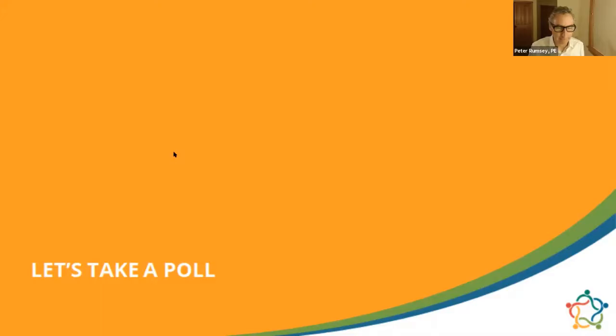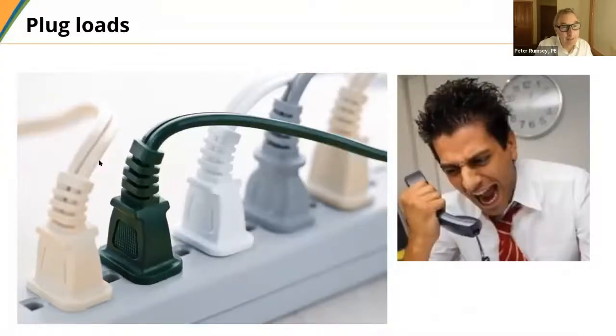Okay. Just a couple more stories that I wanted to share with you. One of them is plug loads really matter, especially in office buildings. And I've worked for a lot of tech companies in India and in the US and other countries as well, and the plug loads are really important. Generally I've measured many buildings, and I find the plug load for computers to be generally about 1 watt per square foot, or 10 watts per square meter, roughly. Sometimes it's a little bit higher, but so often we are demanded to design for 2 or 3 or 4 watts per square foot.